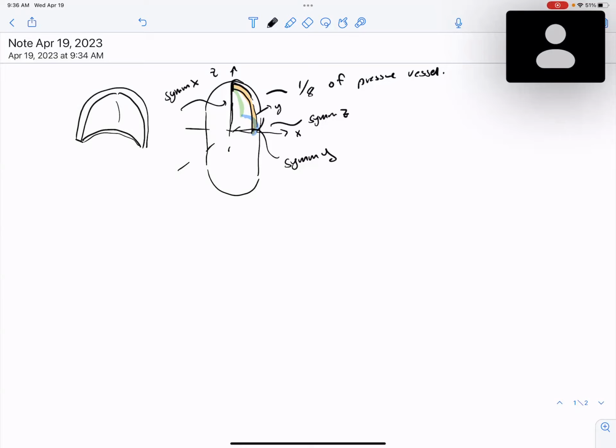And the thing is symmetric, right? So it has these symmetries. You can flip things around and you get the same thing. Did anybody do that? I don't think anybody did. But in the future, if you have a problem with symmetries, use the symmetries, because it saves you a lot of computing power. It saves you a lot of the mesh.